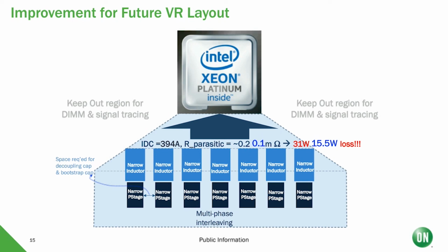And there's a terminology called TDC, which is thermal design current, that each CPU vendor publishes for each CPU. That is the current that we usually design for to operate indefinitely in a typical, say, server or data center environment.